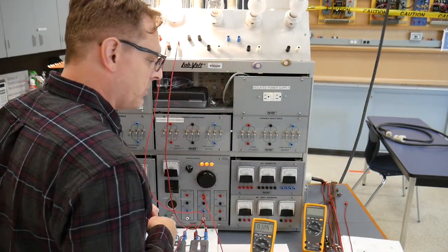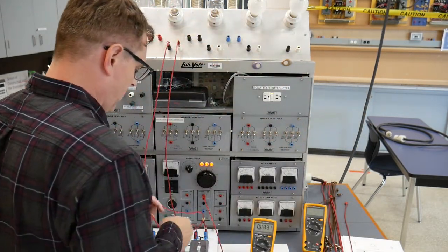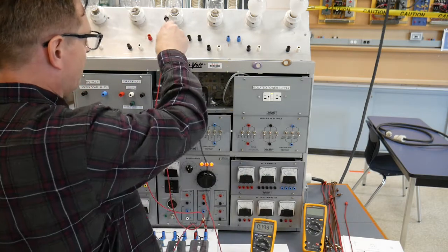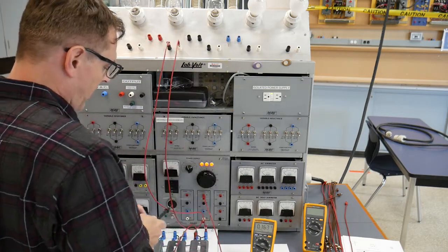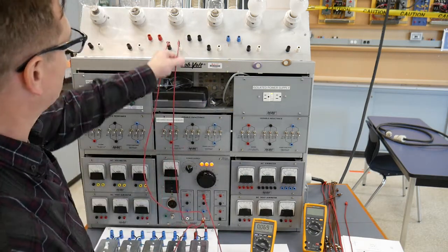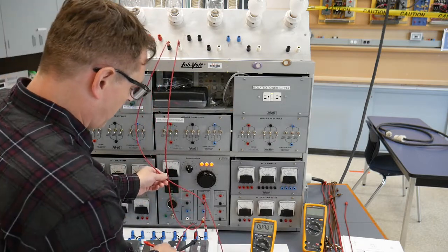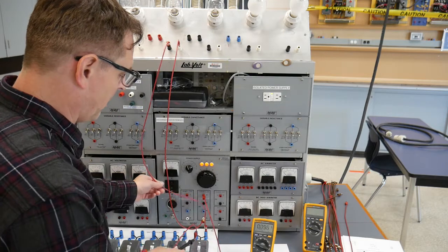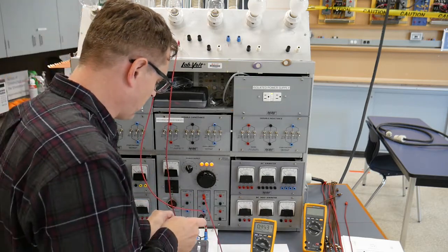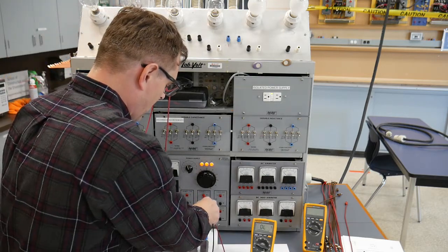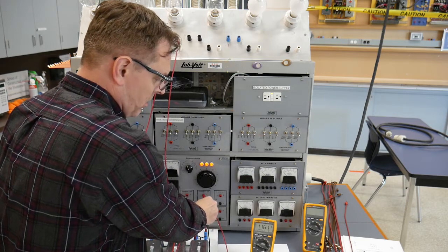And then switch terminals with the switch open. Now we've got a good light bulb up there, so in actual fact we have continuity from the neutral through this light bulb and then back to one side of the switch, and then we have a line conductor to the other side of the switch. So we should see our source voltage across this switch, which we do.